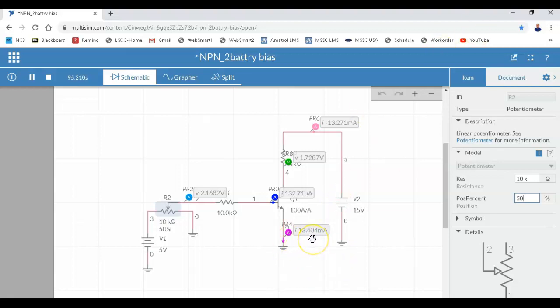No, this is current. This is not voltage. The meter voltage is 0. And all my references, if you looked at the meter when I set it up, if it was saturated, the transistor would drop almost 0. So here's saturated. The transistor has 106 millivolts across it. You understand that? So saturated, it acts like a closed switch.